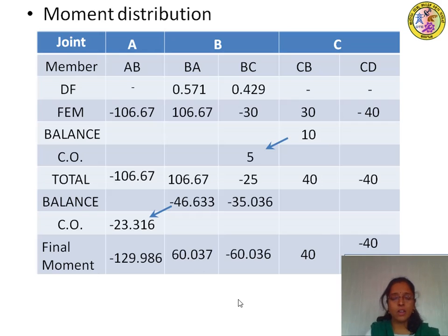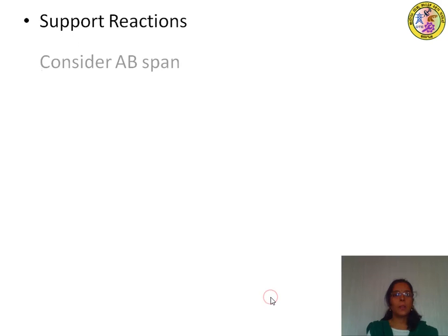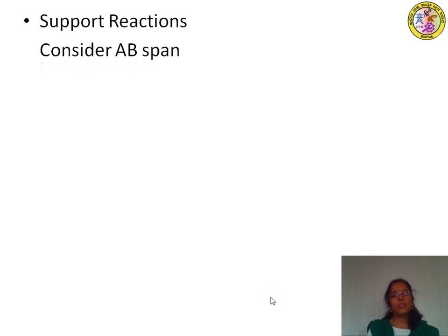Further, we can move ahead to find the support reactions using these end moments. Using these support moments, we will proceed to find the support reactions. So the next step is to find the support reactions. Each support reaction is calculated by considering each span separately.